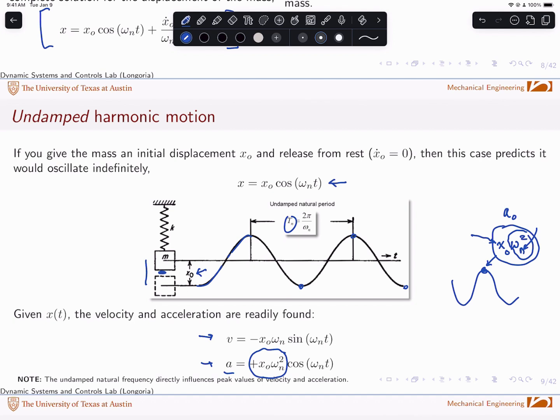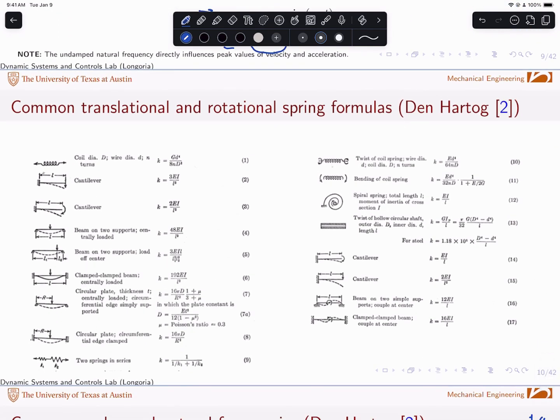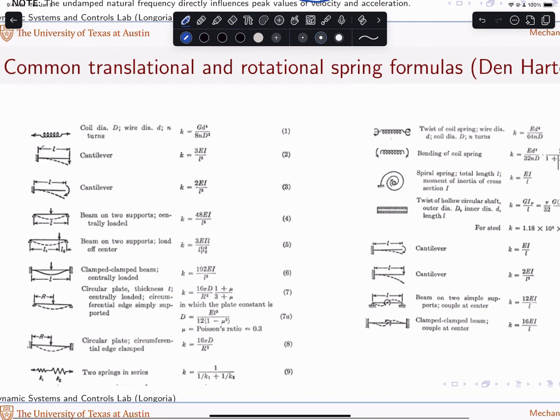So this is how we use these models in thinking about designing experiments and running experiments and so on. A couple more things I want to show you just as a reference. You can come back and look at this. I just gave you some tables here. Whenever you're putting together designs or running experiments, it's really helpful to remember what some stiffnesses are. We're going to be playing with a cantilever beam, and it's this case here. No, it's not this case, sorry. It's this case here. This one shows a beam where you might have a torque on it at the end. Here's the beam where there might be a force. So in this case, say the beam is oscillating. If you had a force here, the stiffness at the end of that beam, you can estimate with this little formula, and that'll be useful to you in this lab.